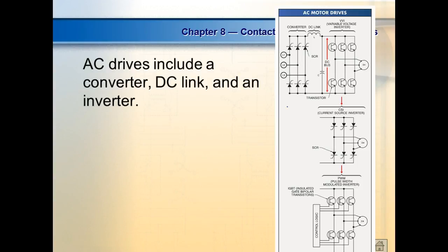This is the SCR drive using these guys here. Normally these would turn the motor on and turn the motor off. But this is the way we did it. And of course now, AC motors are dominating. It used to be DC motors. Why? Because we can control the speed. With AC motors, the only way we could control the speed was to change the number of poles. I don't know what that means, right? Yes, sir. But now we're using solid state devices, we can change it.